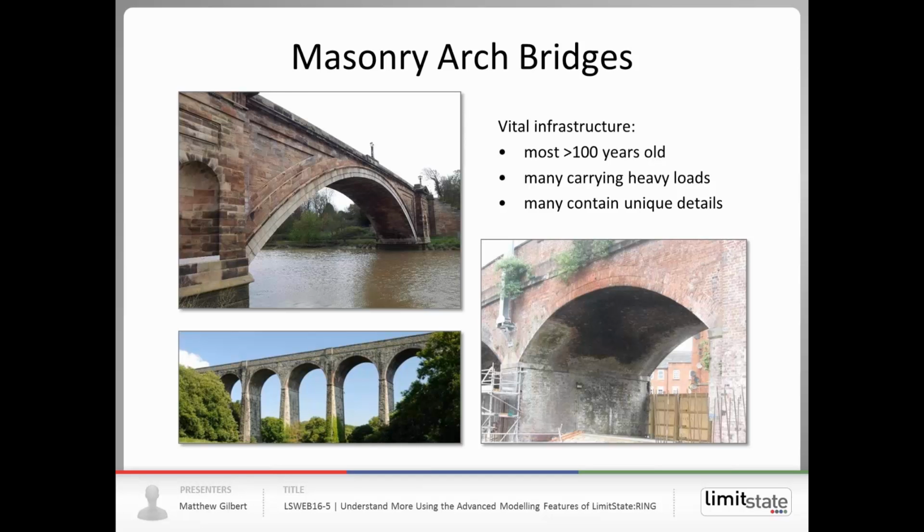However, when we come to assess them, we often find unique details. When I say details, perhaps it's a euphemism for unwanted details: defects, mortar loss, spalled masonry, in the case of multi-ring brickwork arches, partial or full ring separation and so forth. So that kind of suggests that we need reasonably discriminating tools when it comes to assessing them.